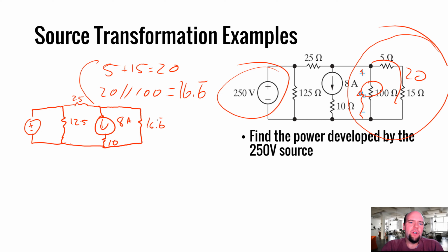And what about transformation? Well, we don't actually have a current supply in parallel with a resistor right now. We have a current supply in series with a 10. But what did we just talk about? When you've got a current supply in series with anything, yeet that sucker. That better not be inappropriate. I'm going to have to Urban Dictionary yeet now. Okay, so get rid of it. Now we've got an 8 amp current supply in parallel with the resistor, so now we can do a simplification.